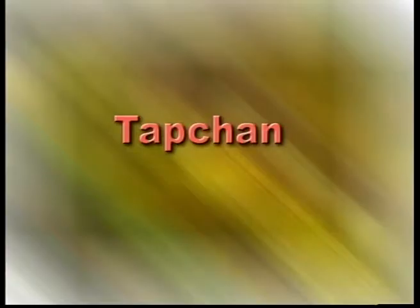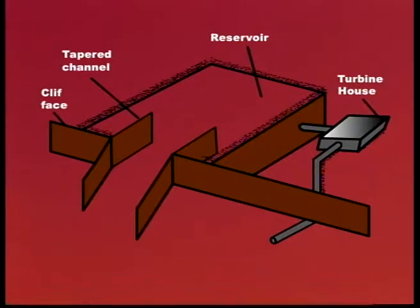There are other devices for extracting wave power from the sea. One is called a tapered channel system, or tapchan as it is normally called, and the operation can be easily seen in the next visual. Here we see that there is a reservoir of water which is connected to the sea through what we call a tapered channel. A tapered channel, as you can see, has a variable width, and the height of the tapered channel also varies.